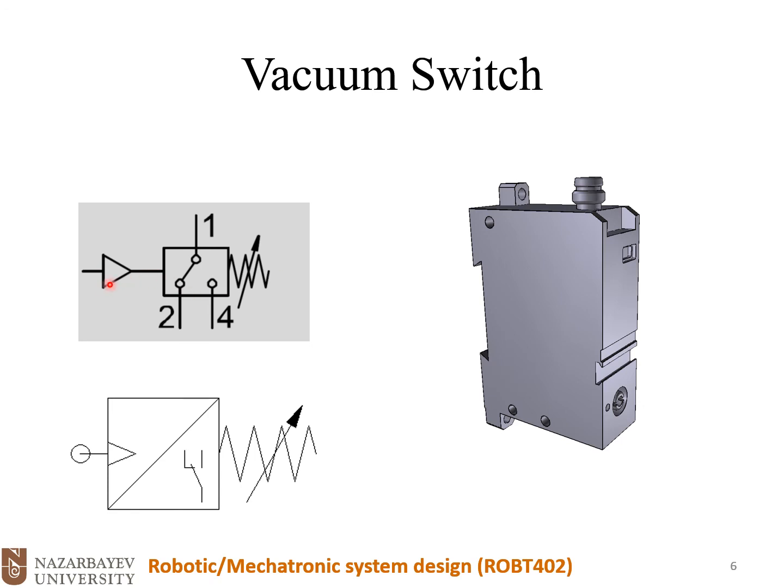So once we have reached a desired vacuum pressure, then the vacuum sensor will close the directional valve. Okay, so that directional valve that you have seen in the previous slides will be closed by the vacuum switch.